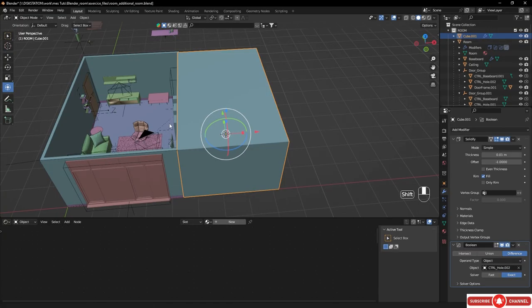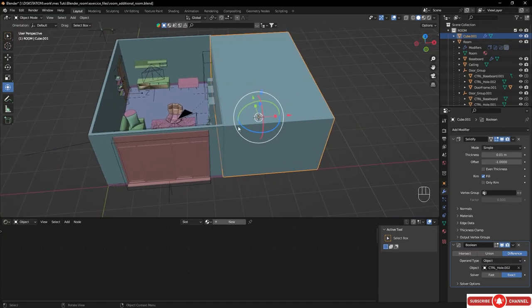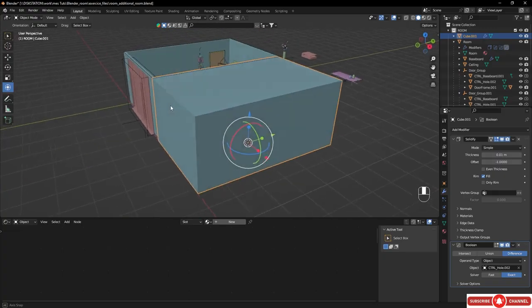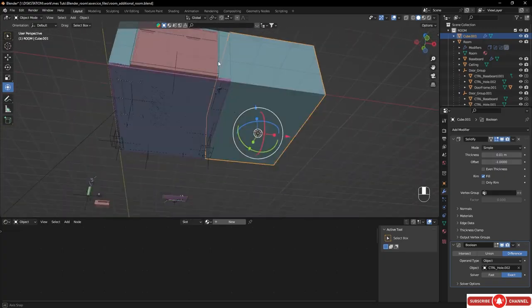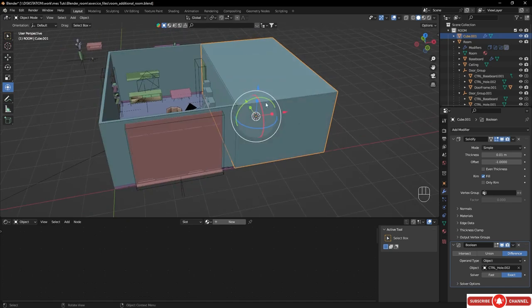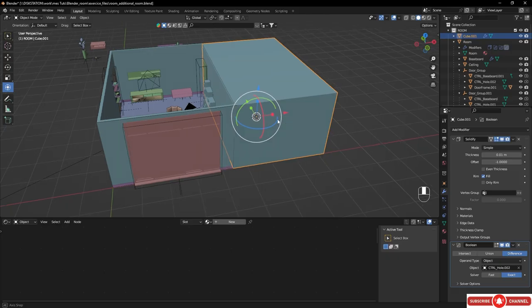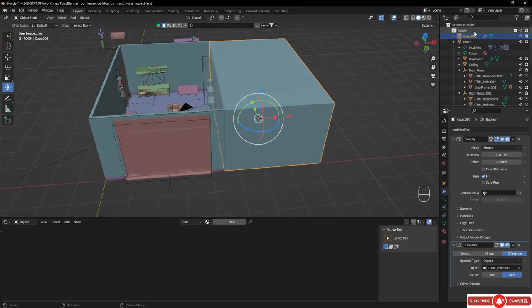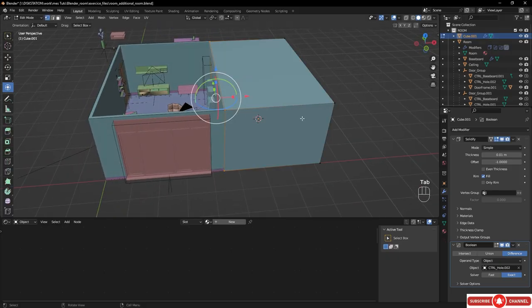So the problem now, if we are going to add lighting again to go back to our shading mode, there will be no light coming in because this is a closed cube after all. So we need to manage the opening here as if it were a room with another window this way. So let's do this. I'm going to take our cube, hit tab, hit 3 on the keyboard to switch to polygon mode.